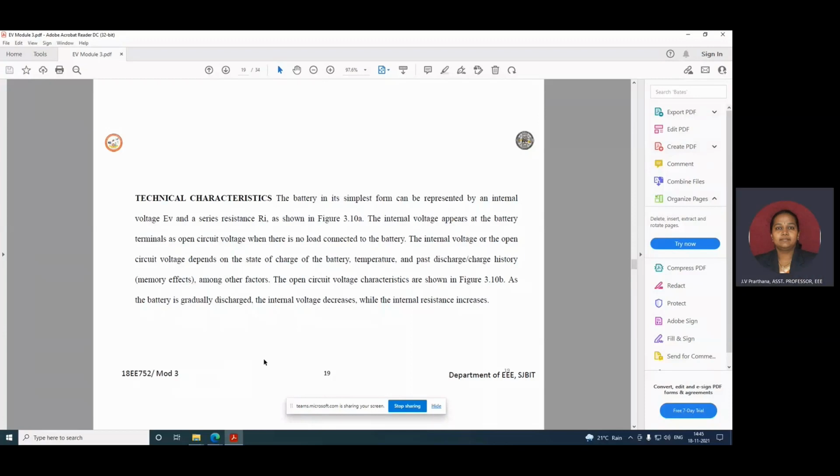Self-discharge rate. Most batteries discharge when left unused, and this is known as self-discharge. This is important as it means some batteries cannot be left for a longer period without using or recharging them. The rate varies with battery type and with other factors such as temperature. Higher temperature generally increases self-discharge.